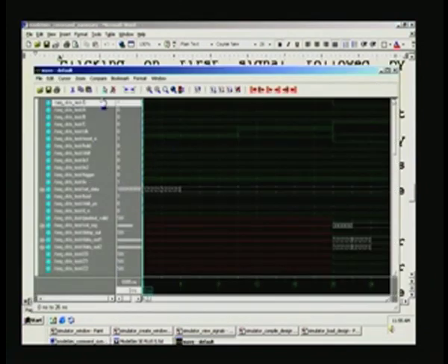Now, what we have done is, let us say D is here, this is what we wanted, and reset is here. Suppose you want reset right on the top. What you do is just click on reset and then, holding the mouse button, drag it right on the top and leave it there. So, the reset n has come over there. This is not the only way, you could have cut here and then pasted here, that is another way. Whatever signals are there right on this page within the vicinity, you can drag like this, and otherwise you may have to use find, which we will do for the signals not available here. Let us say we want next clock, so we will put it there.